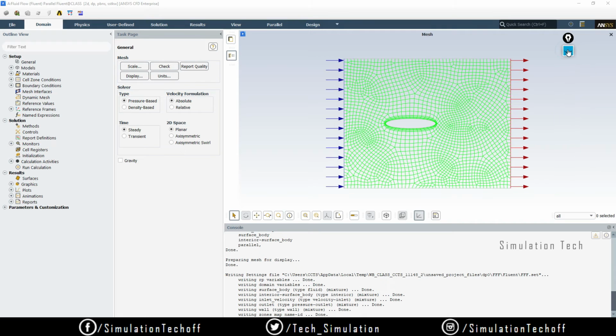Okay, in Ansys Workbench itself, we clearly studied the process. That is, we have three types of process. One is pre-processing, solving, and post-processing. What pre-processing does is the creation of the model, applying boundary conditions, and meshing. These we call pre-processing. Once this part is completed, the second part, the solving part, is where the problem gets solved by the numerical solvers. Once the problem is solved, we get numerical data. We can't directly interpret that data, right? So obviously we need a certain environment to decode that particular data and view the results in terms of contours, colored images, or other graphical formats, right? That is why we call it the post-processing environment.